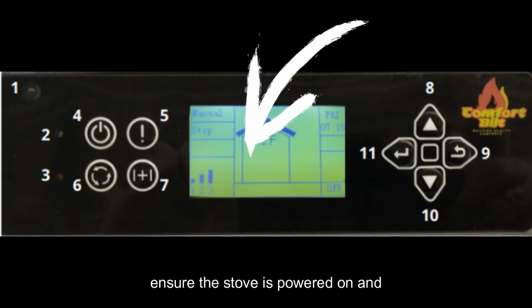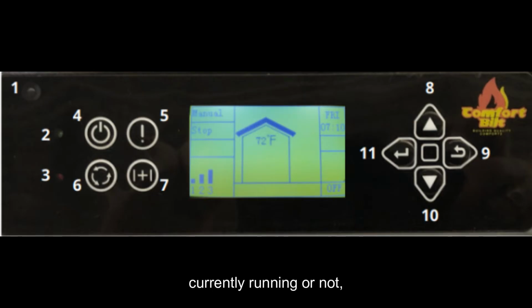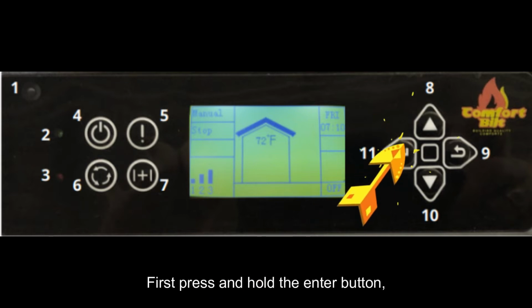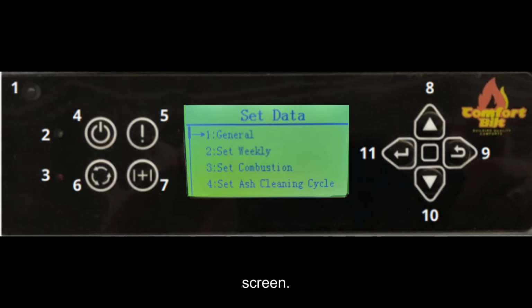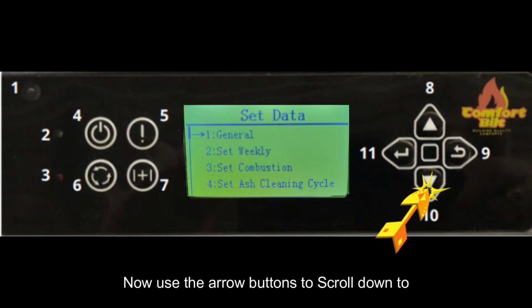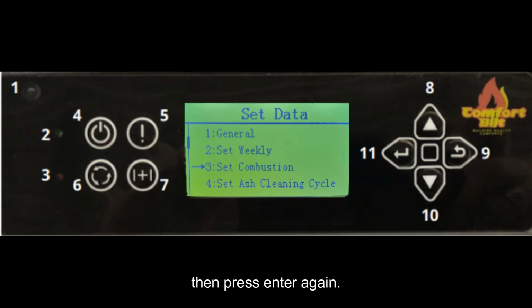Step 1. Ensure the stove is powered on and displaying the home screen. It does not matter whether the stove is currently running or not. As long as the screen is lit, you can follow these steps. First, press and hold the Enter button, which is this left arrow, until the Set Data menu appears on the screen. Now, use the arrow buttons to scroll down to option number 3, Set Combustion, then press Enter again.